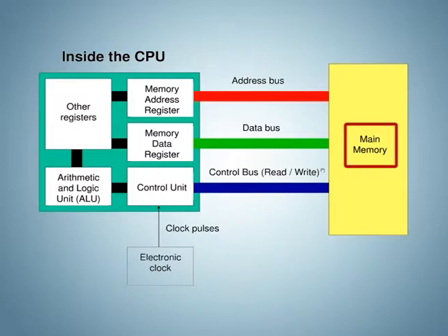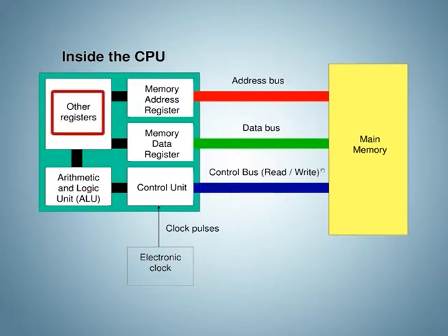If the instruction requires operations to be performed by the ALU, it is necessary to obtain the operands. The ALU cannot add 2 numbers unless the 2 numbers are given as input to the ALU. If an operand resides in the memory, it has to be fetched by sending its address to the MAR and initiating a read operation. The desired operand is brought from memory and stored in the MDR. It then is transferred to the ALU. The ALU performs the operation and generates the result. The result may either be stored in one of the registers or a memory location.